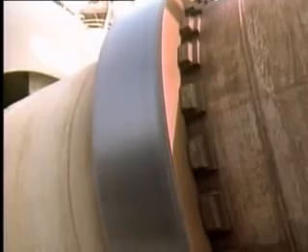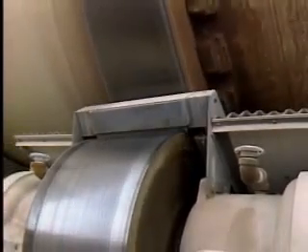This heat and the kiln's weight would quickly melt and wipe away ordinary grease. This graphite lubricant is in the form of a solid block. Because it's a solid, there's no danger of its melting away and leaving the metal surfaces unprotected.